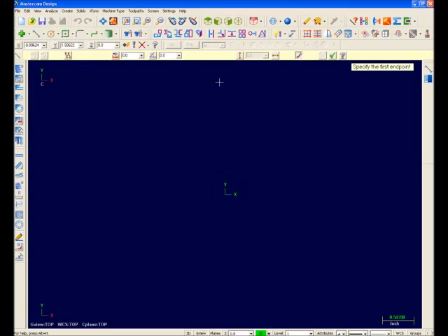I want to begin with my line on the origin, so I'll select the fast point button from the auto cursor ribbon bar. The fast point mode can also be entered by hitting the space bar on the keyboard. This fast point mode allows value inputs to be entered in the same manner as previous versions of Mastercam while still supporting traditional math functions. So I'll type 0, 0, 0 and enter.